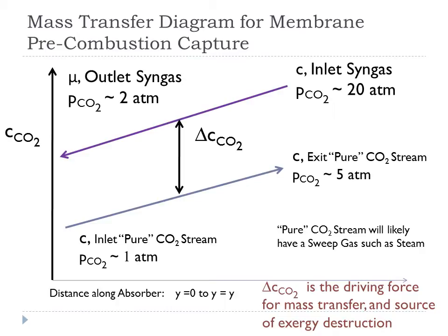So we have a system now where in this pre-combustion one, before we've done any work, we already have partial pressure of CO2 between, let's say, 5 and 10 atmospheres. That's a lot better than the case before, where it was some number between 0.01 and 0.05 atmospheres. We're a lot closer to 150 atmospheres.